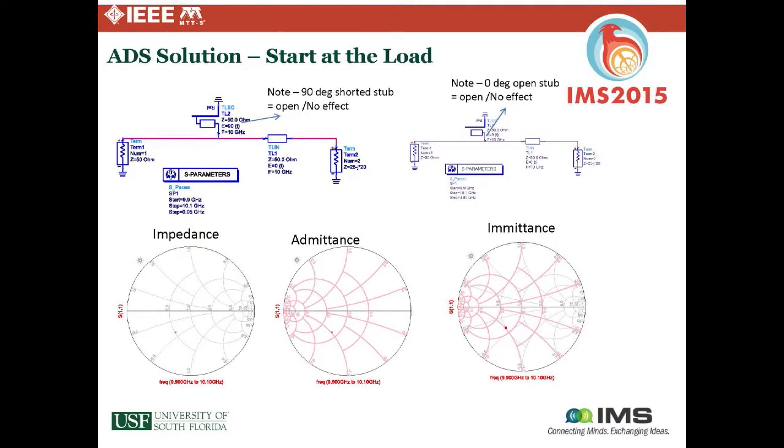So here is just showing after we add a transmission line of the right length, which we can find using tuning. Since we're adding a shunt element, we want to be in the admittance chart like this, so that we're going to be on the G = 1 circle. So this is the result we want, the same view on the 3 different charts. And then what we're getting set up for is adding this length here to bring us into a match.